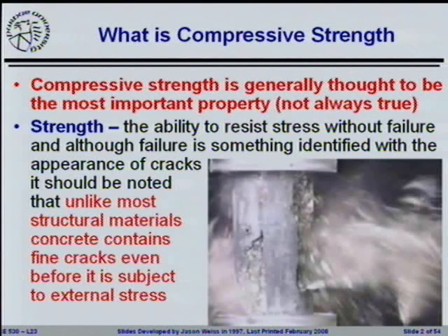So what is compressive strength? Right? F prime C. All right? Compressive strength is generally thought to be the most important property. I would say this is true if your structure is going to fail in compression. If your structure is not failing in compression, this may or may not be true.